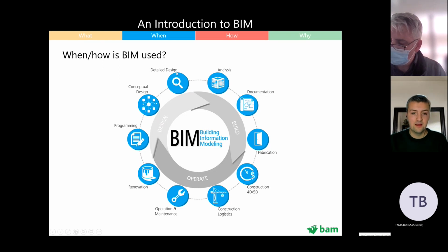That's then obviously refined in detailed design analysis. So again, this comes back to the intelligence of the software. Once you've started to build your building in 3D in the BIM software, there are energy tools and lighting tools built in, so you can start doing an energy analysis. What's heat retention going to be like in this building? It runs the calculations for you based on the materials that you've said are going to be in the walls, how big the windows are, and so on. All that is built into the software, so it's really, really powerful.